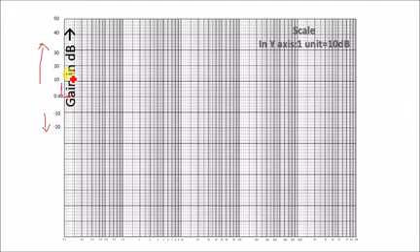After that, what you need to do, we need to plot the corner frequency. Here the first corner frequency, that is omega L, lower, which is 0.5, which we have chosen. Okay, the next corner frequency will be 5 radian per second. The next will be at 50 radian per second, and we have chosen another omega H, which will be 100 radian per second.